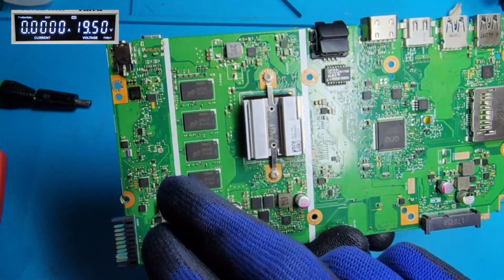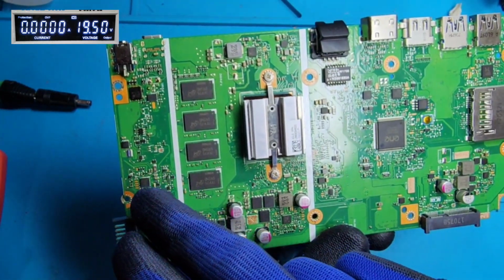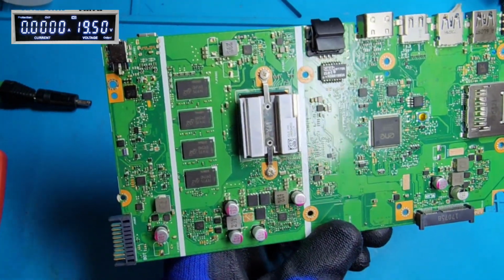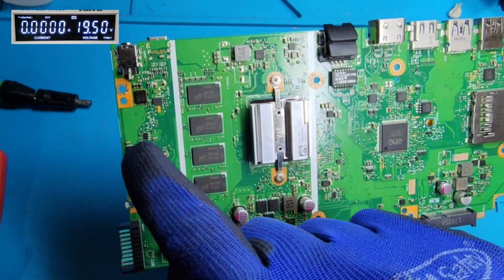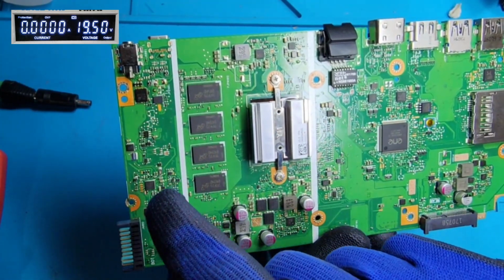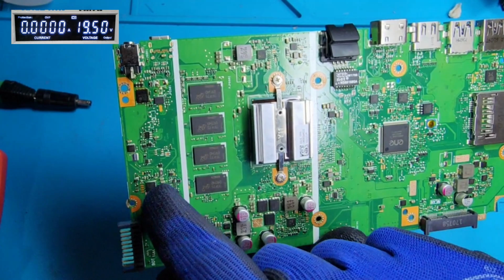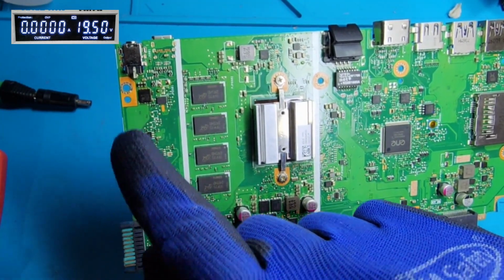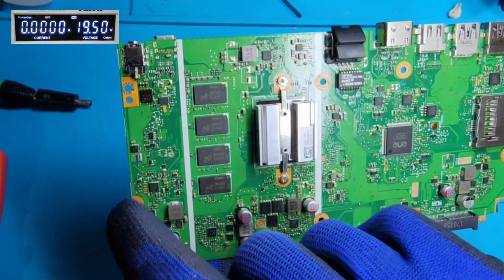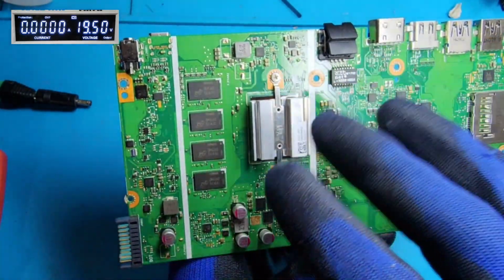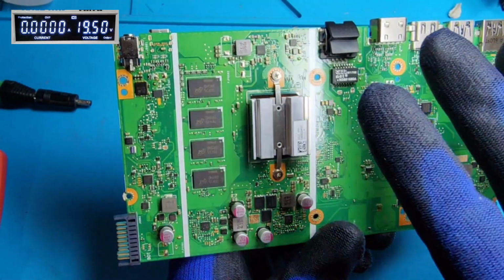So it's very important for the charger IC, and also it is very important to protect your components in this motherboard here. So do not always remove these two MOSFETs. If the charger IC is not driving these two MOSFETs, find the problem why it is not driving them. You should not remove this MOSFET and put a jumper wire, it is really dangerous for your motherboard here. At any time your components can get shorted.